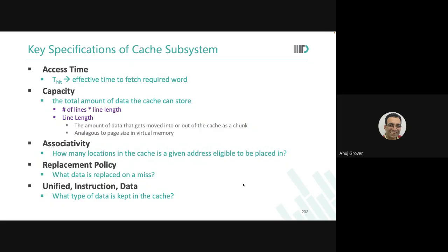But if you're designing something for very primitive applications, for example, just a small sensor node, then the power consumption, the area, and the cost of the chip would be of very high priority. You may want to go to direct mapped also. And for cases where you require super high performance, you do not even go to set associative. You say, okay, I will go to fully associative. Any data can go anywhere. Is that okay?